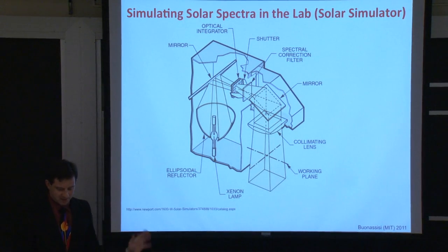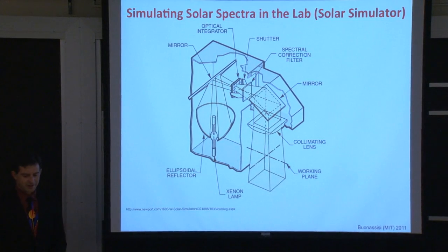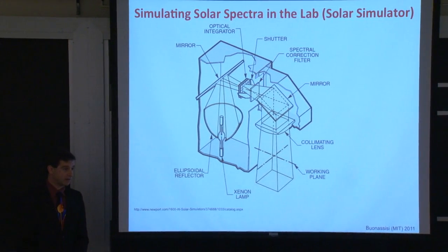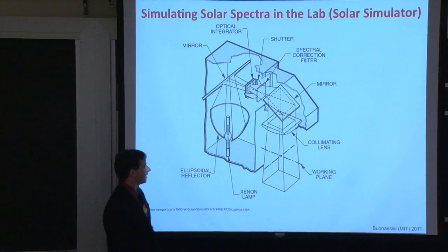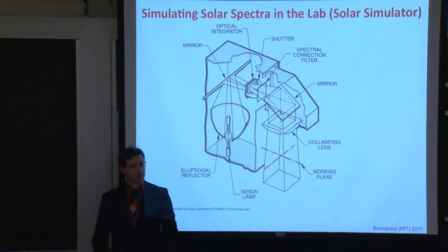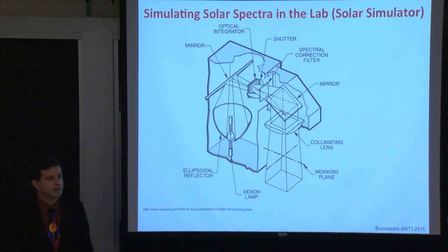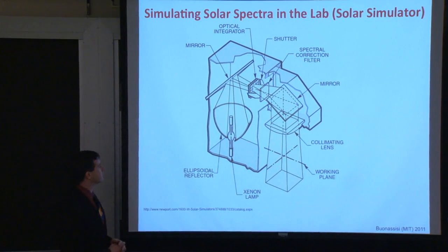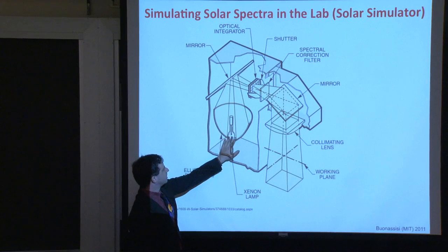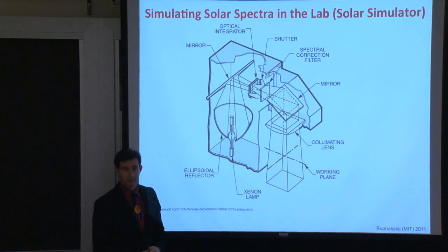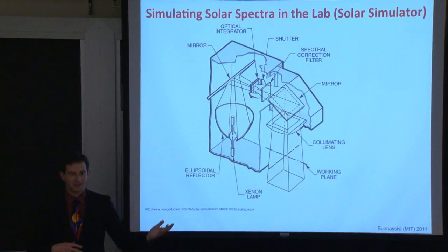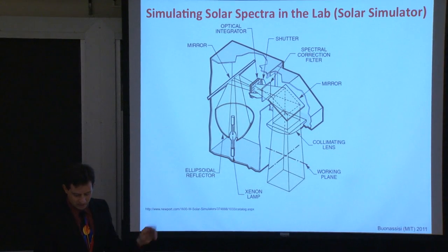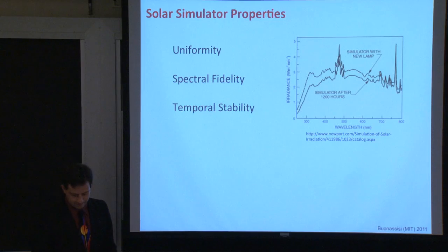So another interesting thing to note here is that we have quasi-planar light coming in at the end of this optics train. But if we're going to be measuring, for example, concentrating solar cell apparatus, it's much more important to have a higher degree of planarity of the incoming light, and then other optics would be used. One might envision, for instance, increasing the distance between the light source and the actual sample, or the optical path length between the collimating mirror and the sample.